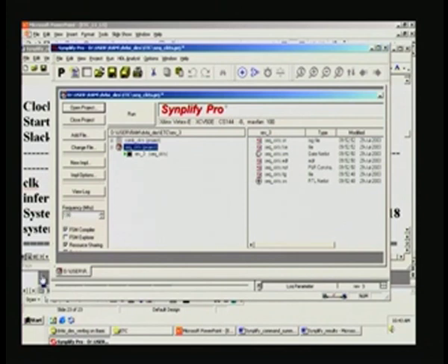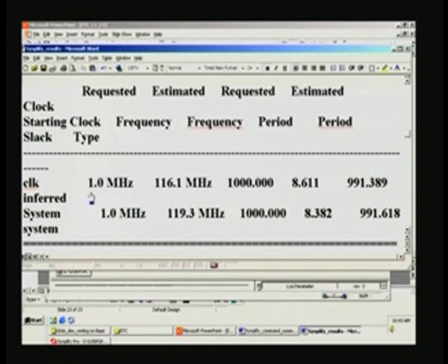Although it was 0, and 0 conveys no meaning, it put it as 1 megahertz, but that is not a handicap here, because whatever is the actual thing achieved only will be reported here, that is what counts. In fact, we would have normally asked for 100 megahertz. Surprisingly, it has given 116 megahertz for this sequential circuit, whereas we got around 86 megahertz for combinational circuits.